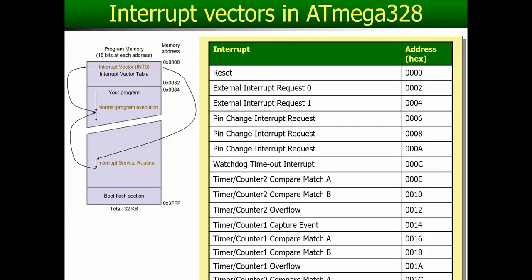And now what happens is every time I'm interrupted, I know that after interruption, I'll be executing another function. It's called an interrupt service routine. And how would I know where to jump in memory to execute that code? Where is that code located? This main program should know. Your loop function should know in case of the Arduino IDE. So it goes to a table first, and it picks up the starting address of the memory location which holds the code that needs to be executed in response to that interrupt.